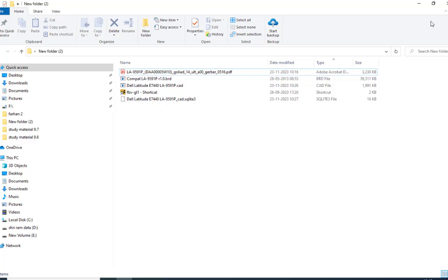Another advantage of using a board viewer is checking the signal connectivity, the tracks. So these are the advantages of using the board viewer. In this session we are going to learn how to use the board viewer, how to test, how to trace the signal, how to trace or find the components, as well as using it with the schematic diagram. So first we open the schematic diagram.